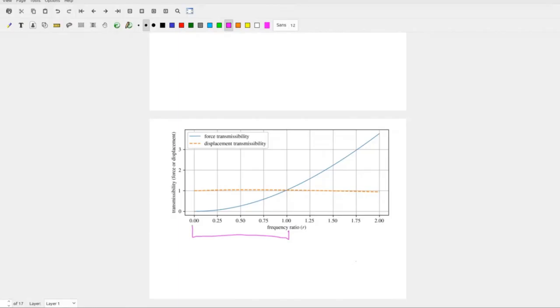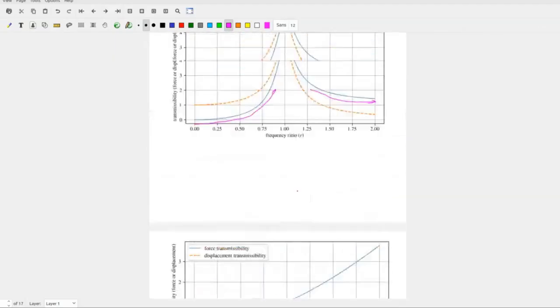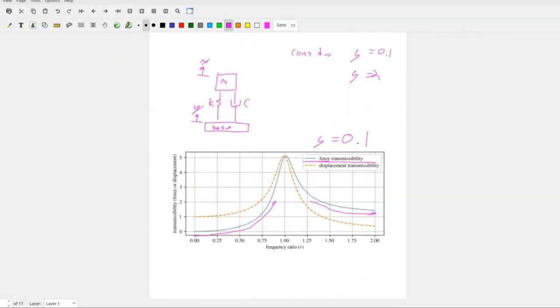So what if displacement is my limiting factor? For an overdamped case, it doesn't really matter too much unless you have a very tight clearance, right? But for an underdamped case, at very high frequencies, you get very little displacement, right?